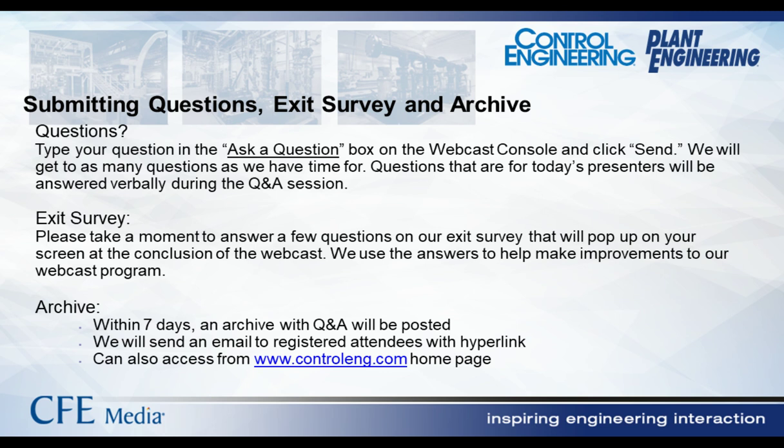Just some general guidelines, the top 2, safety rated monitored stop and speed and separation monitoring, are typically going to be used in instances where higher speeds or heavier loads are required. The power and force limiting and the hand guiding robots are usually used in situations where you've got lighter loads and slower speeds involved.